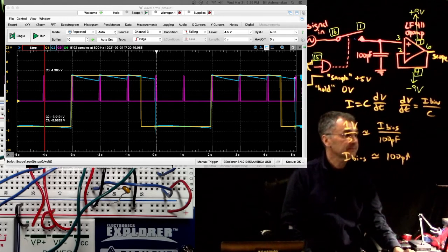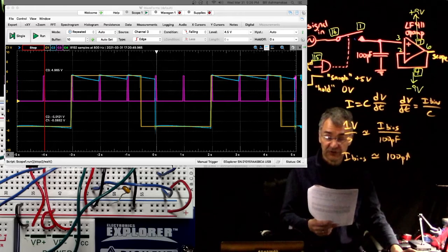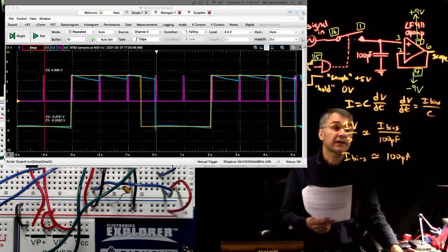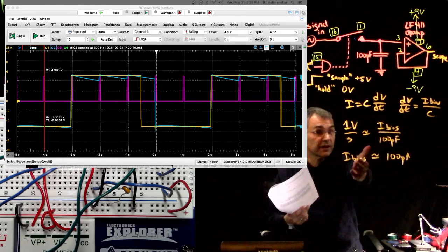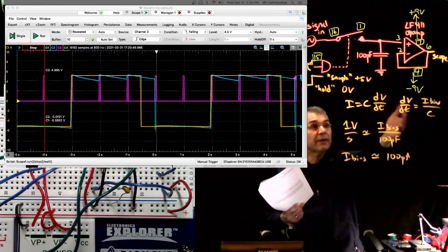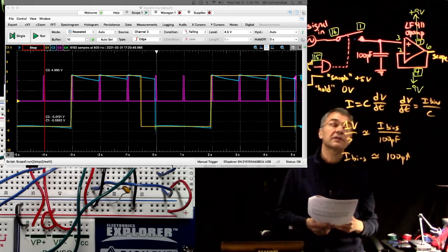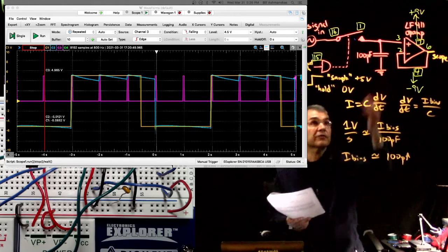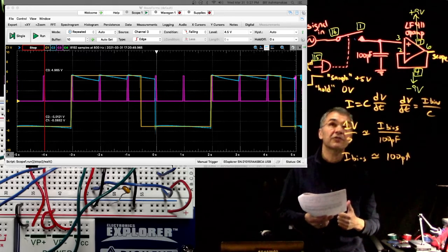That's cool. Oh, by the way, Tom has this question: can you infer from the droop of the signal when the switch is in the hold position what leakage paths dominate? Well, I think the answer is it's I bias of the 411 OpAmp. Let's just suppose that it is. Then it makes sense because our dV/dt is consistent with what you expect from the bias current. The question is, is there some other leakage path that might make sense?